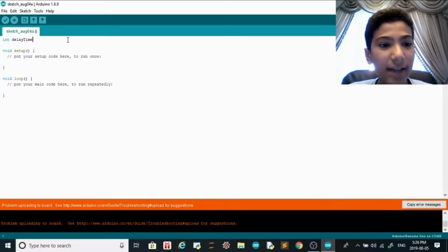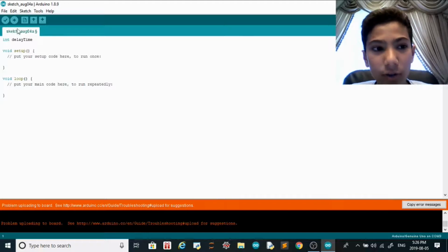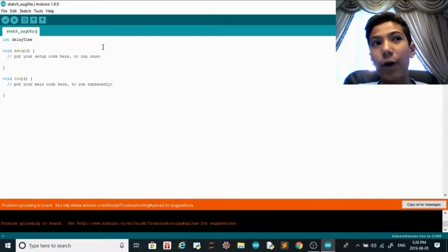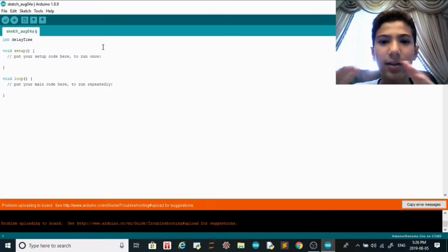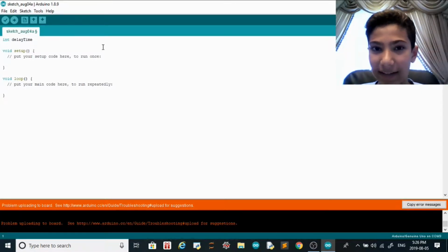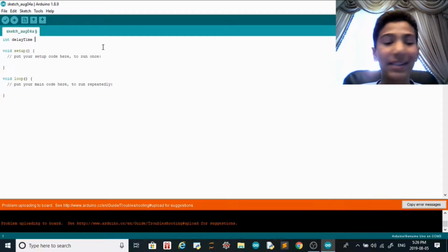So it's called delay time. You don't need a variable to do delay, but variables are very important, because let's say you put multiple delays of 500. The 500 is in milliseconds, not seconds. So if you put 500 milliseconds, it's half a second.